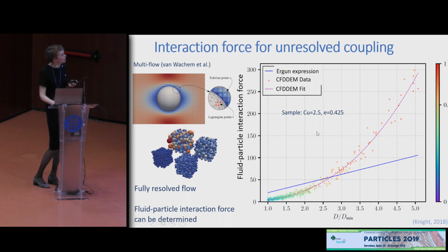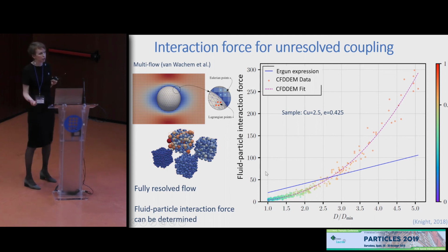And what we can see is that the expressions used in the unresolved flow simulations do not give a good match to the drag on the particles across the full range of particle sizes in our sample. They underpredict the drag on the large particles and overpredict the drag on the small grains. And this is an issue when we're thinking about erosion.